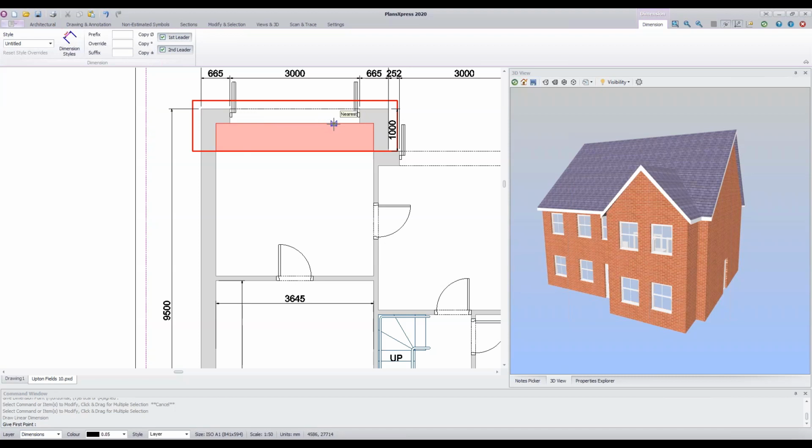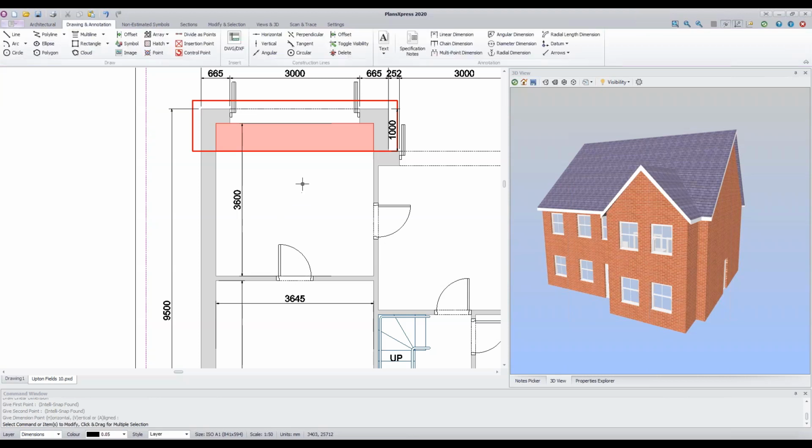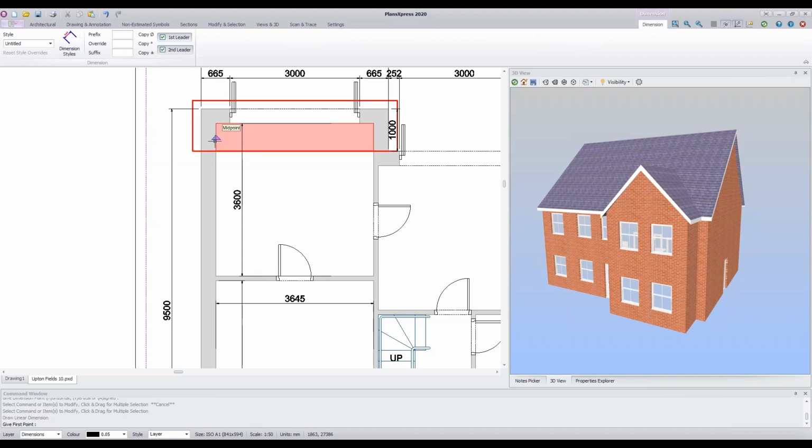Perhaps easiest just to find a nearest snap point on the inside of one of your walls, then find the perpendicular snap point on the opposite side of the room, left click again, place your dimension line, left click again to place it. Right click to repeat the process.